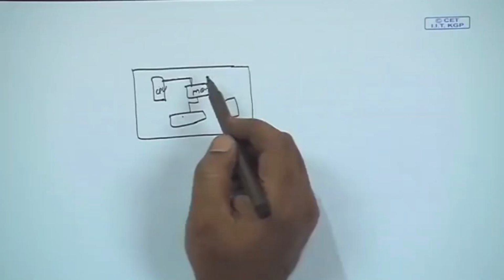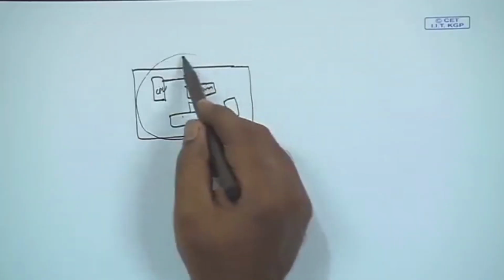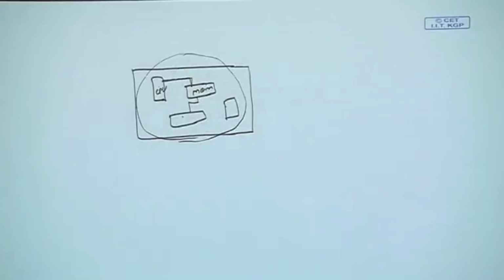Okay. So, latency: though the CPU and memory are both semiconductor devices, it is due to the physical interconnect that we have outside the chip, that may be copper or maybe some other metal. So, that is going to introduce the delay. So, how to break this speed barrier? This barrier may be broken if this entire thing is fabricated on a single die.